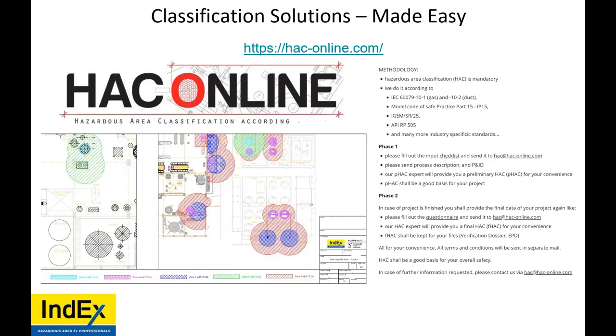from the manufacturer to the hazardous area classification engineer, to the designer, to procurement, to maintenance and inspections of the complete life cycle of the facility. 2B plus H2 identified on the hazardous area classification drawing, and that type of equipment is most ideal. Yes, you can identify it as 2C, but at the very beginning, we showed you an example that was in Europe, and I have many other examples that would show that this happens continuously, wasted time, money, and talking about the issue endlessly.